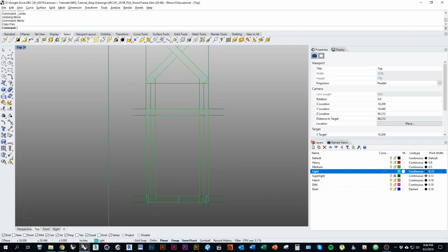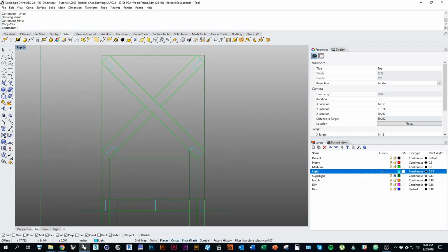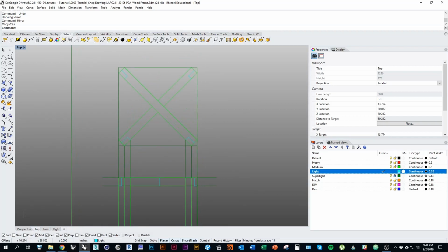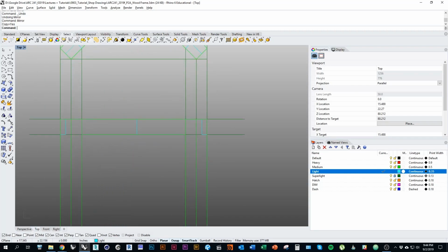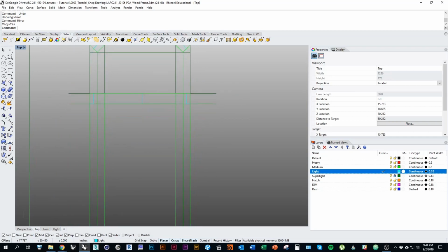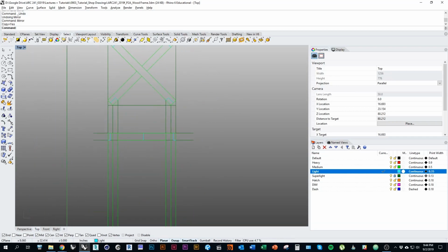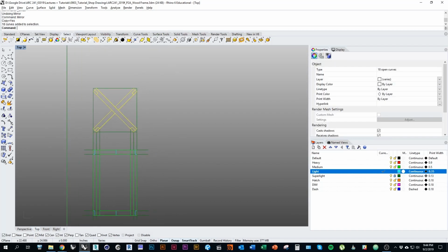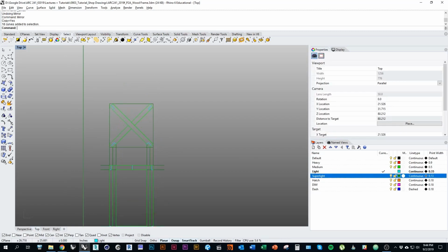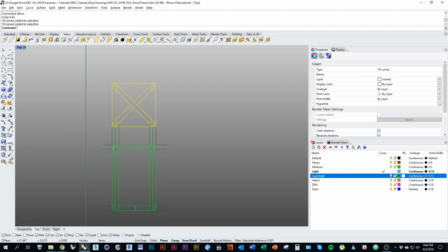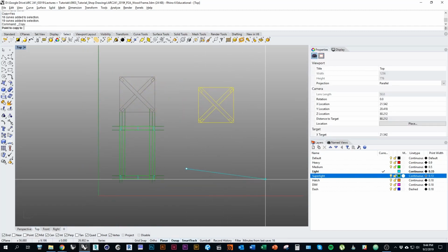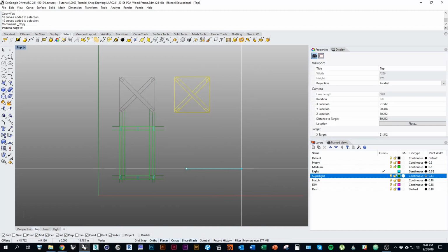Now, as I talked about a little bit in the drawing up here in the plan, it's actually going to make the most sense for us to show all the joints and how they work in both elevations. So in order to understand how it would work in the next elevation, I'll unlock my layer super light. I'm going to just select my plan and make a copy of it. So I'll hit copy, or type in copy, just click anywhere and hold shift, move it over like that,